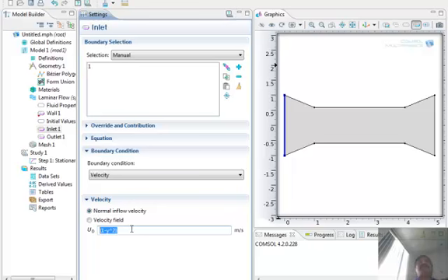So you can put in complicated expressions like that in any form that you are filling in. For example, viscosity. I want to put an expression for viscosity there as a function of temperature or concentration or gradient of the velocities. You can throw in an expression there. Wherever it accepts numbers, it also accepts an expression or even a MATLAB function, M file. Then it will go to that M file and calculate that property. Okay, good. So that got cleared up.